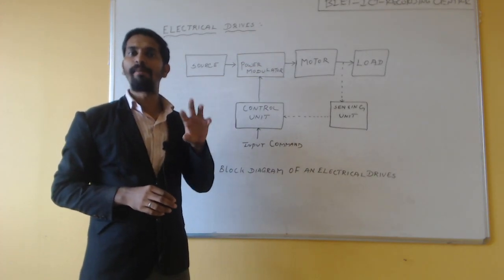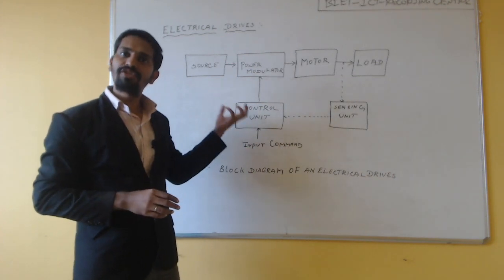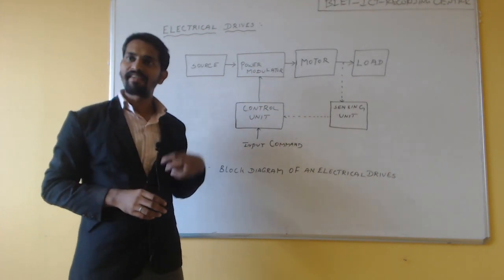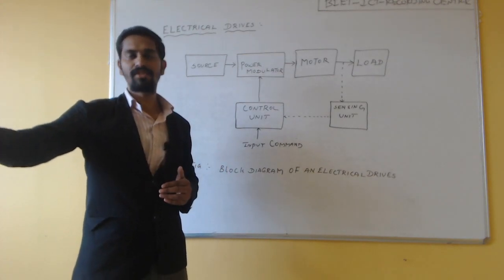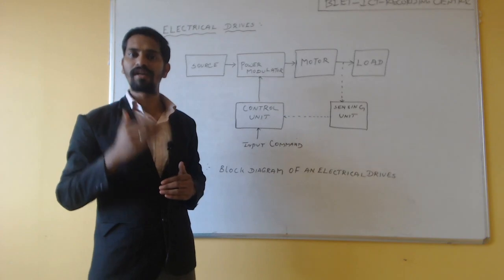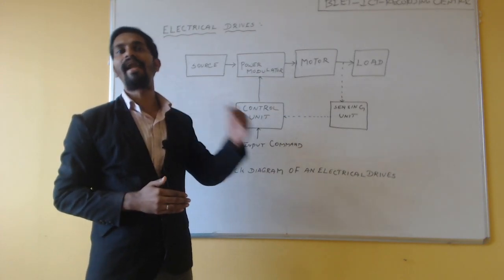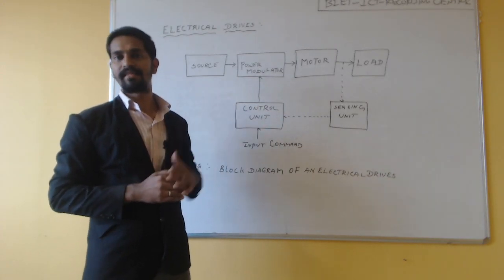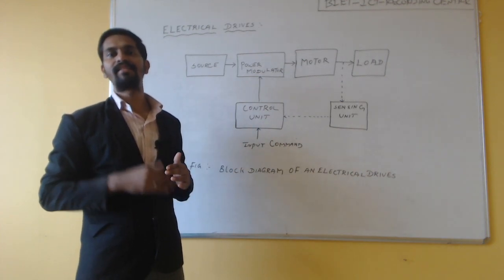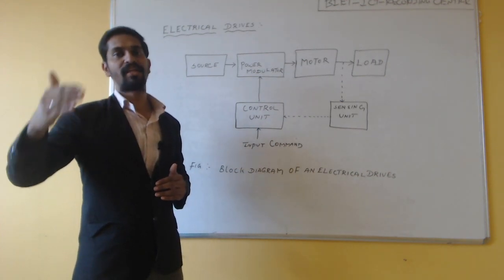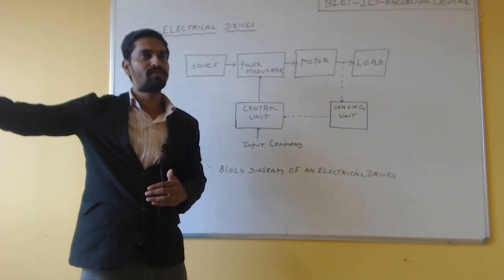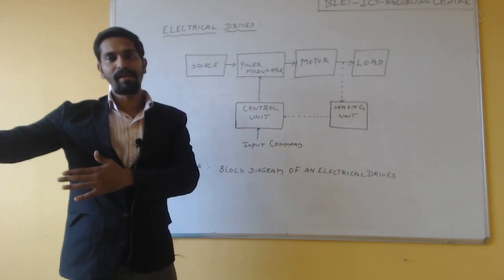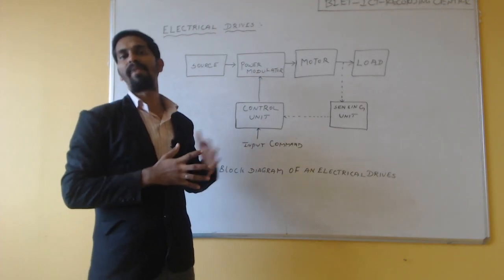If our application is DC related, we can go for a DC source, that is, batteries are required to provide the electrical energy for the systems. The DC range, based on the application, is 4 volt, 8 volt, 12 volt, 24 volt, 48 volt. So depending upon our applications, we can choose the power supply.